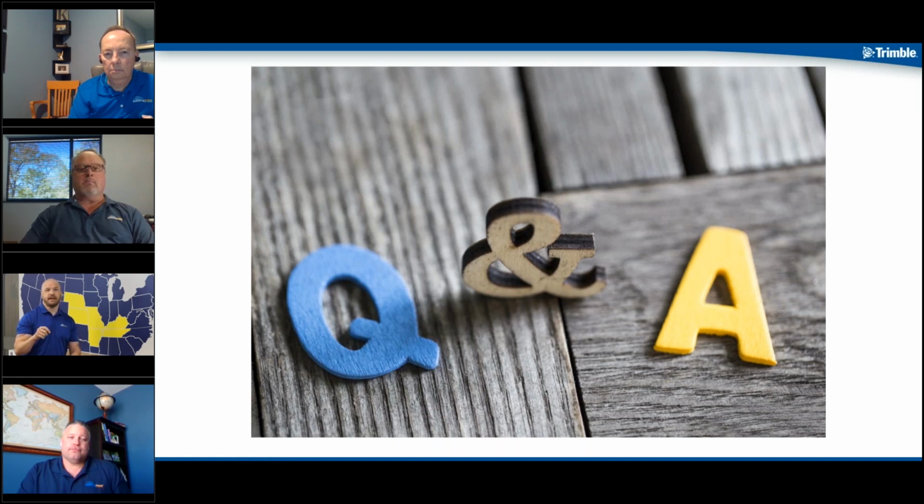So in lieu of going to layout, I'm going to go up to collect, and I'm going to shoot my laser up to that point in the adjacent building and aim it at that target, record that data, and that's going to give me an X, Y, and a Z that's going to be associated with all of my civil control points on my X, Y, and Z. So that way it is spatially located to my site,